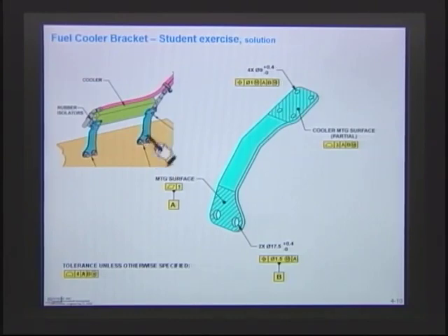Now if they tell you, well, we don't want any kind of a fixture, we just want to be able to put it up and bolt it up, well, you're going to have a pretty hard time, right? I mean, you're going to almost have to dowel this into the frame. And the reason is that you see how close those holes are and how far that distance is away?